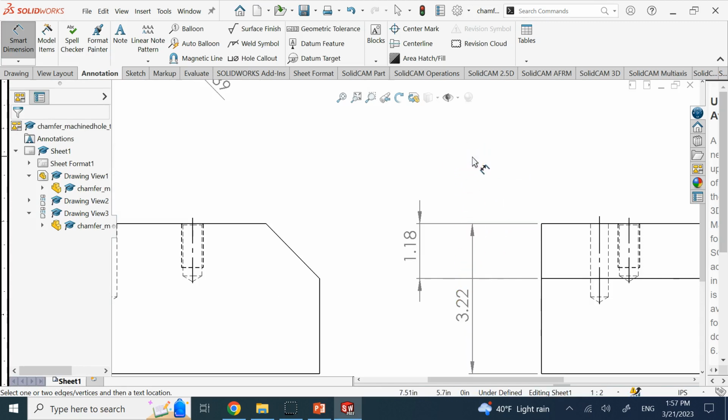But what is intersecting what here? Your dimension line is intersecting an extension line for 118. So can a dimension line and an extension line intersect? Well, we try our very best not for this to happen. We don't want even a dimension and an extension line to cross each other.